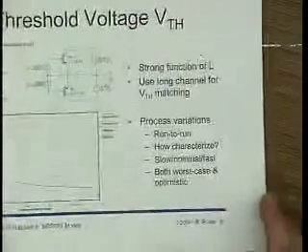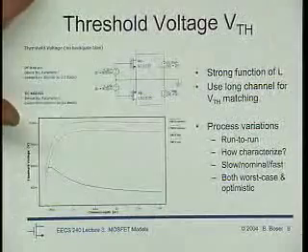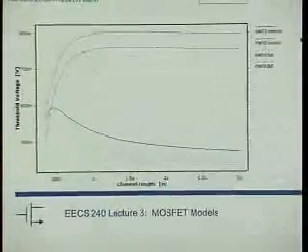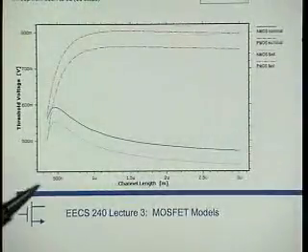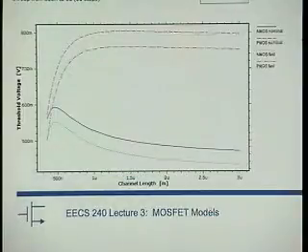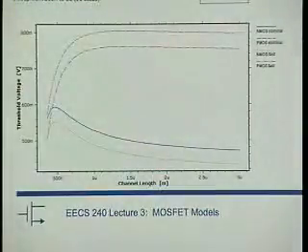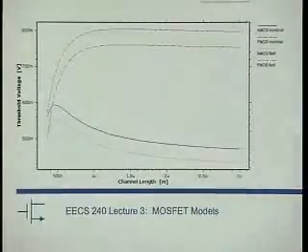Okay, let's look at these things just a little bit. Okay, so here is the threshold voltage. If you can zoom in a little bit just to this area, thank you. Here is. So all modern versions of SPICE, they have a way that you can ask not just what is the current that's flowing through my transistor, but you can also actually ask it what it calculated internally as what the threshold voltage was, or the transconductances of the device. I use that liberally, and I suggest you do also, because then you can know all these things, right?